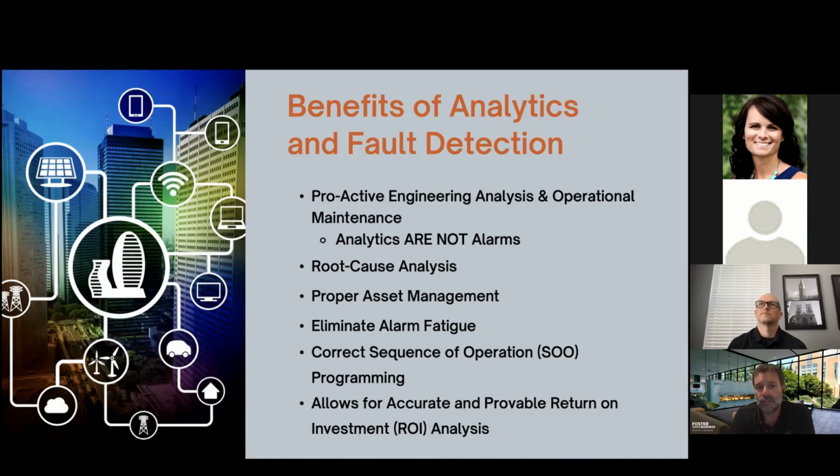So it really gives you a good opportunity to look at that root cause and eliminate some alarm fatigue, right? So now you can get rid of that alarm that keeps on going off, because at the end of the day, a lot of building automation system alarms get ignored. And if they're getting ignored, then there's really no value in those alarms taking place.